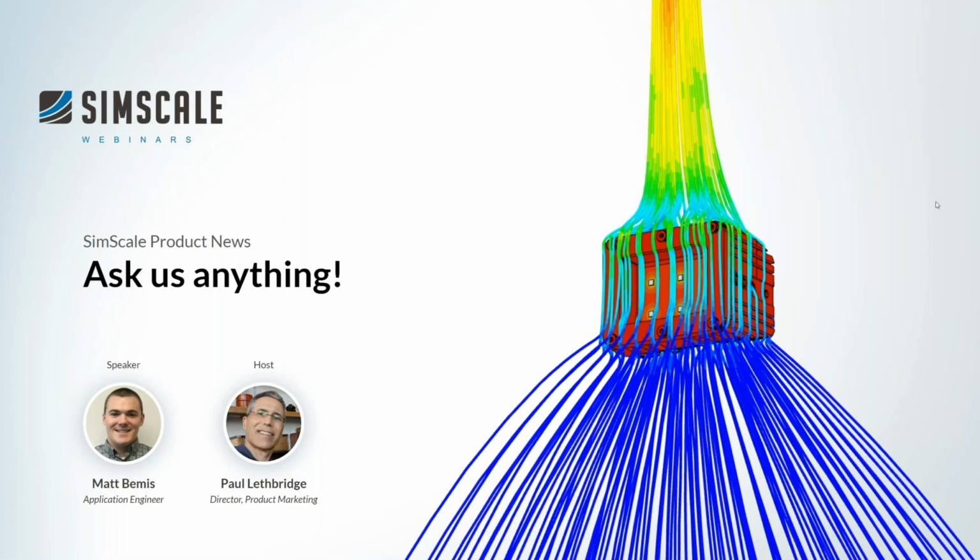So it's based on the mesh settings I use there, but ultimately the background cell count usually ends up staying pretty low because we are not capturing that very, very small detail, like the gaps between the gasket and the housing, like I showed earlier. So these are less computationally expensive than your normal CHT simulations you'll run for electronics within SimScale. If you have experience with that, certainly know this will be much less in core hours.